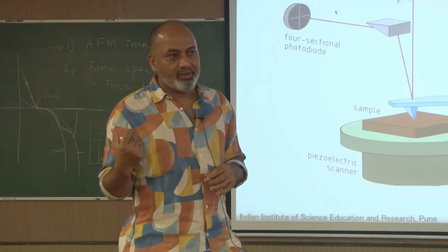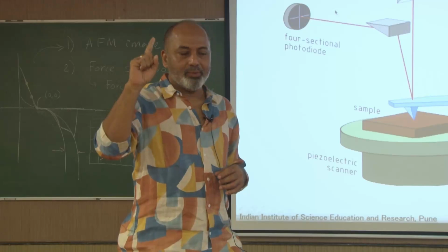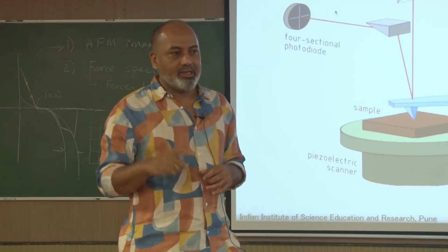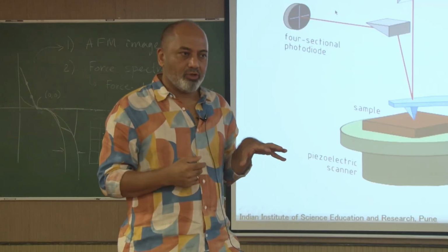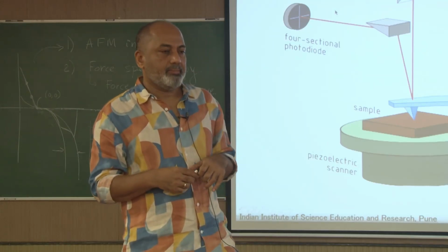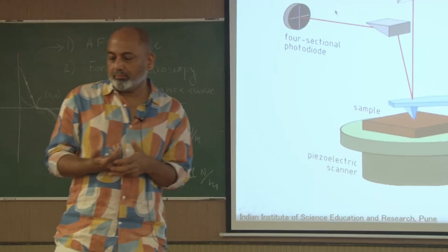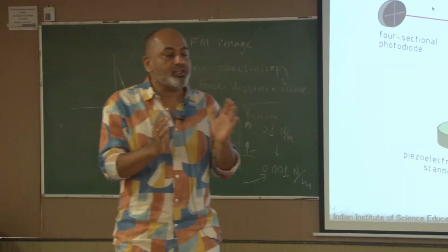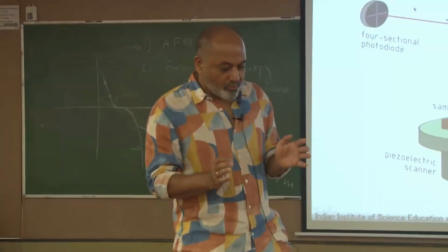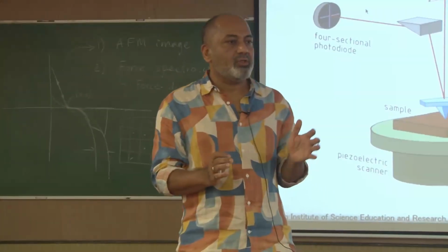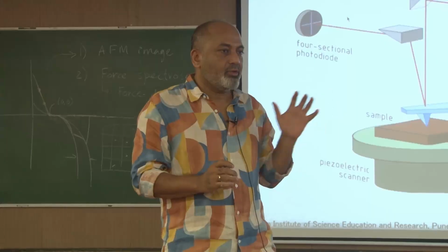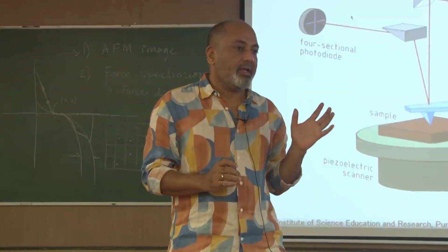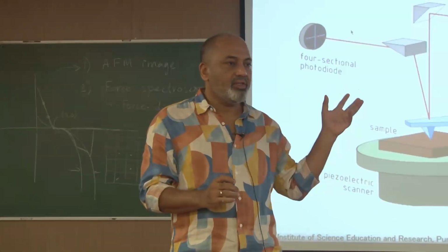We'll talk about it in my lecture, whichever number it is. We do this in the lab quite regularly, on cells but also on gels. Cells are generally not linearly elastic, they are viscoelastic. You have to take a constitutive equation, assuming a standard linear solid, a power law rheology, a Kelvin-Voigt model or whatever, or in contact mechanics you use DMT, JKR, all that.